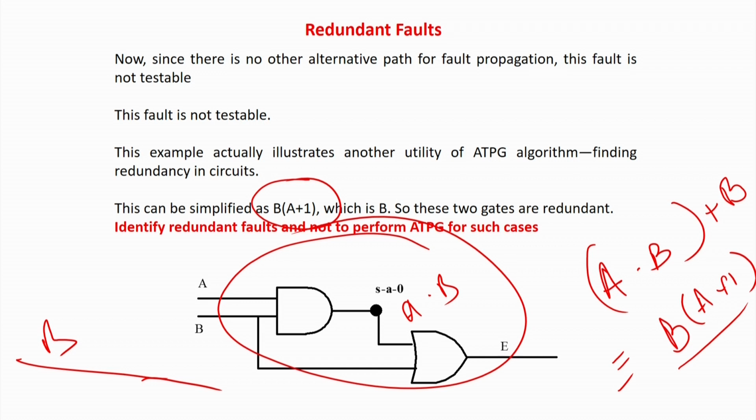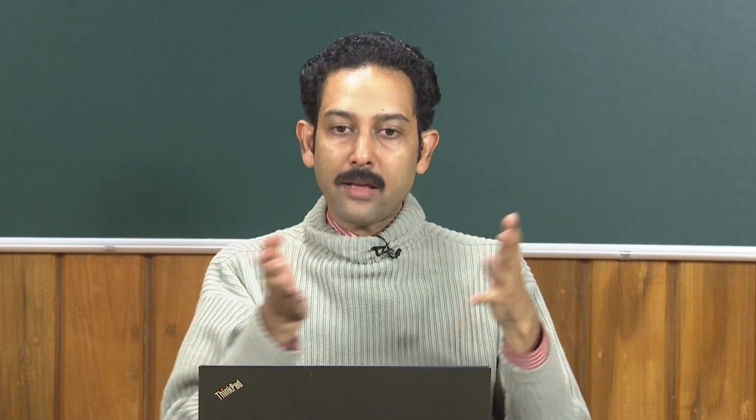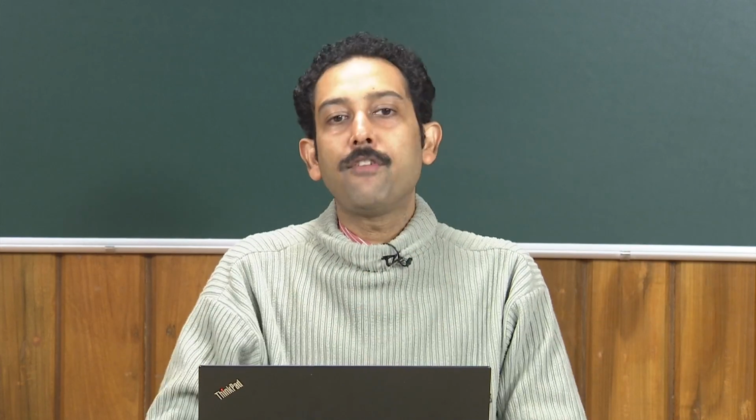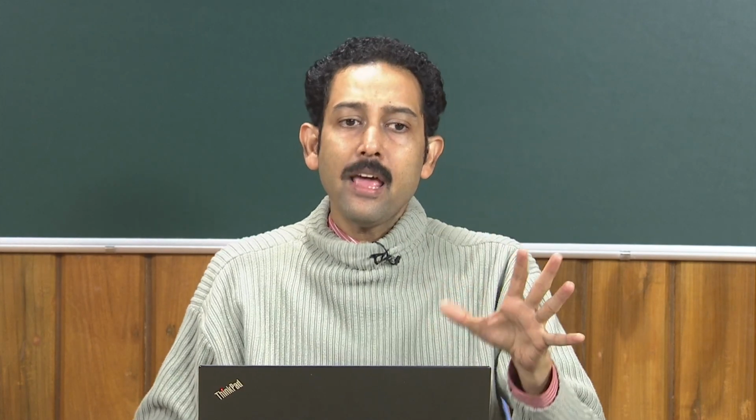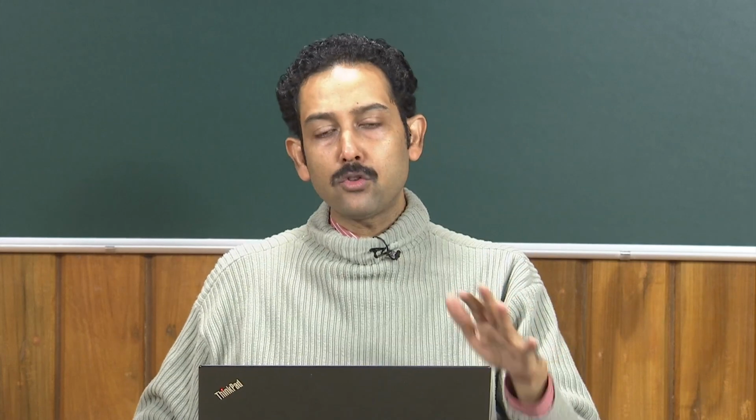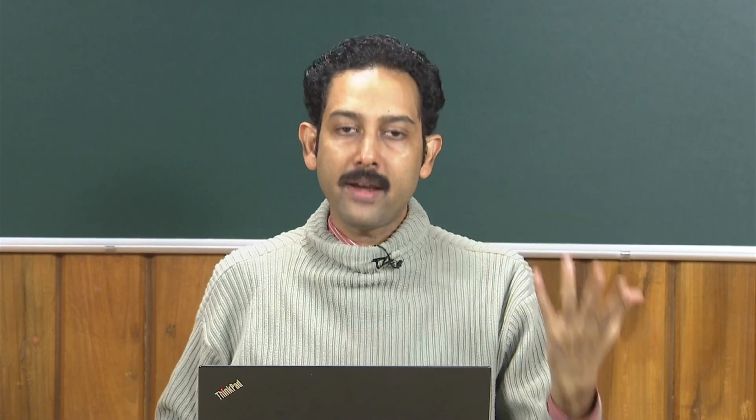In VLSI design, sometimes a lot of redundancies are put in to avoid hazards and to put buffering arrangements, etc. Generally, to avoid hazards, people would sometimes put redundant gates. But somebody should identify the redundant circuits beforehand, because in a real optimal VLSI design, which has already been covered by Chandan sir in the case of design, you generally do not give any redundant circuits, because they do no job but eat up your area overhead. Such cases are generally kept for a very explicit purpose, because no automation or design tool will give you a redundant circuit.